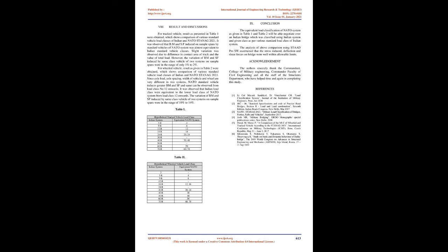For analytical analysis purposes, the Bailey bridge was modeled and the above load classes were applied. First the Indian load classes were applied on the model and analysis was carried out. Thereafter, equivalent NATO load classes were applied on the same model and analysis was carried out to check the adequacy of a bridge span to carry both Indian and NATO standard vehicles.